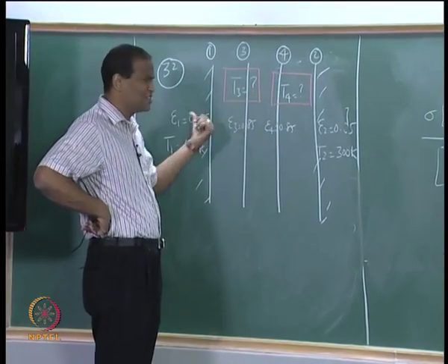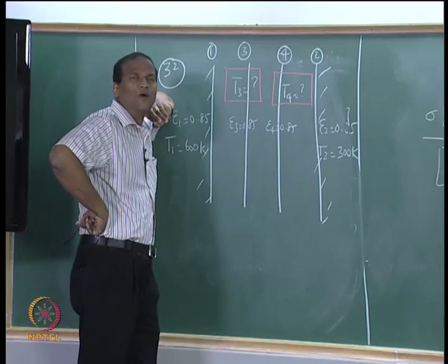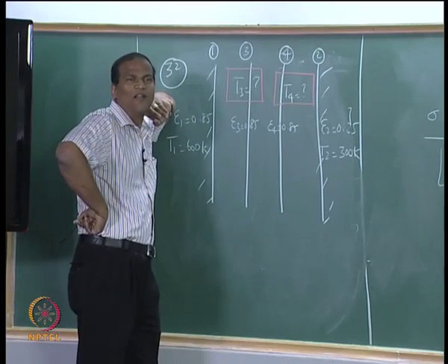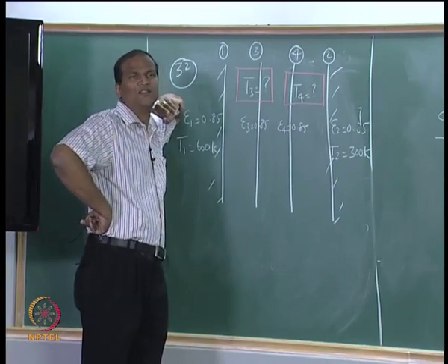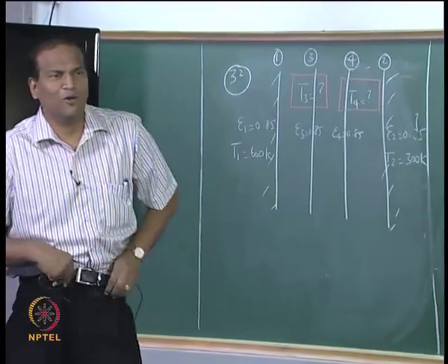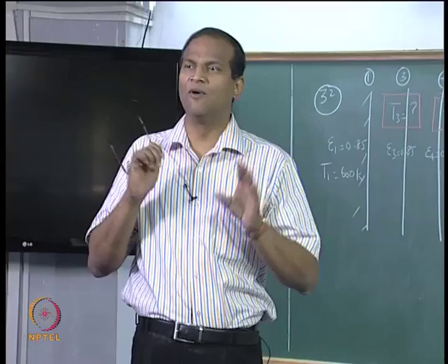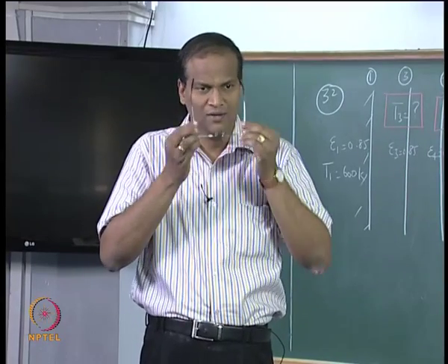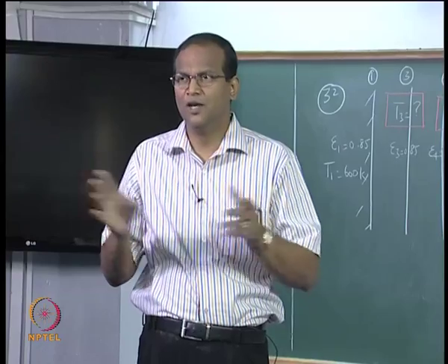And then if each of these is different from epsilon 1 and epsilon 2, so what he is saying is he is qualifying whatever I told a little earlier further. I told you they have to be black, but he says so long as all are having equal emissivity, whatever I told, (T1 to the power of 4 plus T2 to the power of 4) divided by 2, whole to the power of 0.25 holds, correct? That you can call it as TEQ. What is EQ? Equilibrium temperature.